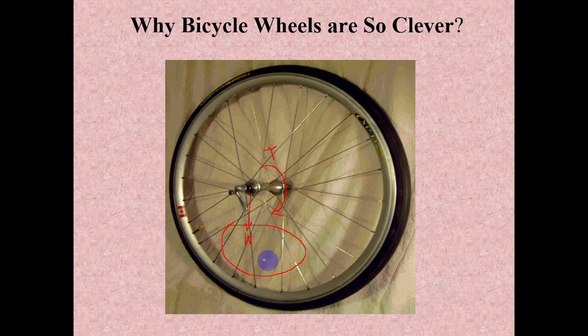So when it starts rotating, this loading and unloading will happen. This high stress will come one by one in all the spokes once it starts rotating. Due to this load W, this part of the spokes will get some tension and this part will get some compression. Since these spokes are not unstressed, they are all pre-stressed columns. Basically, when we use the nipples here, they tighten all the spokes uniformly.